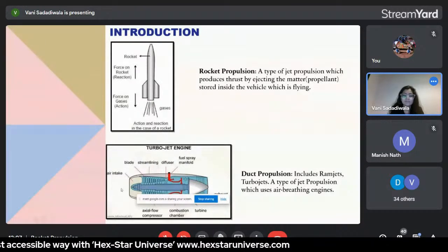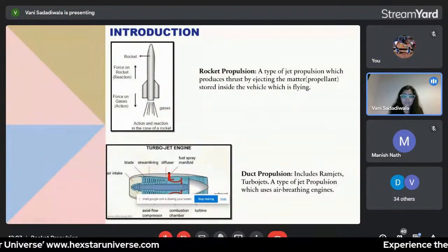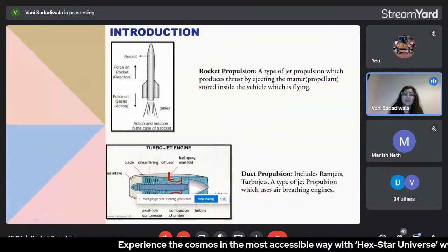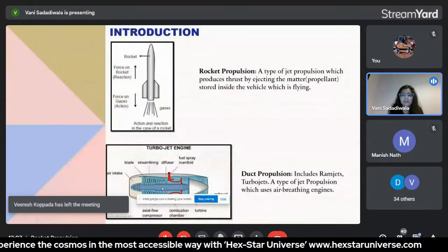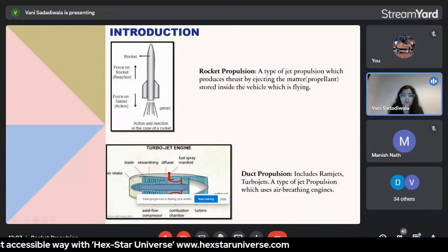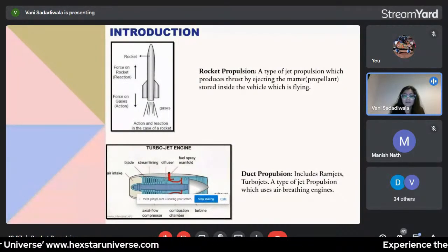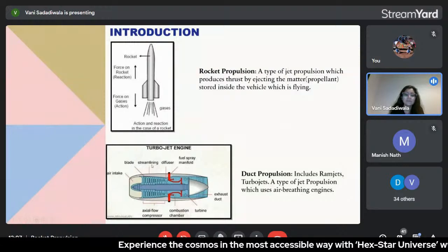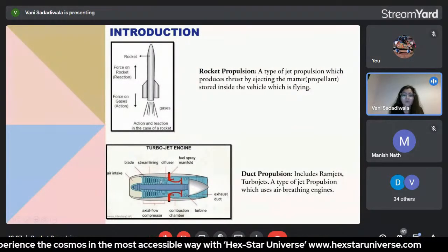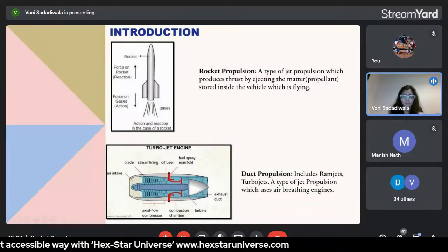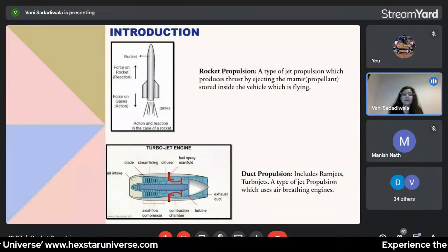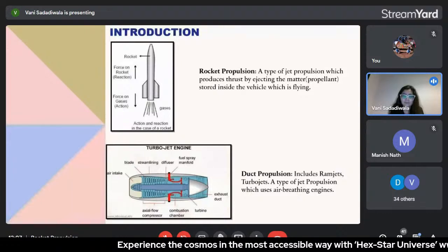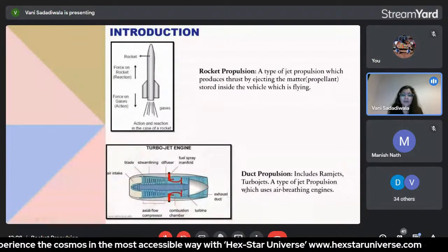If we consider the air intake section, air is sucked in through the air intake, which then moves to the blades of the axial flow compressor, in which the air is pressurized, so the pressure is increased whereas the volume is decreased. Further on, in the combustion chamber, there are fuel spray manifolds which inject fuel into the compressed air, forming a compressed fuel-air mixture, and it moves ahead to the turbine. In the turbine, due to the movement of the rotor and stator blades, the air flows out through the exhaust duct with high velocity and in a highly pressurized manner.